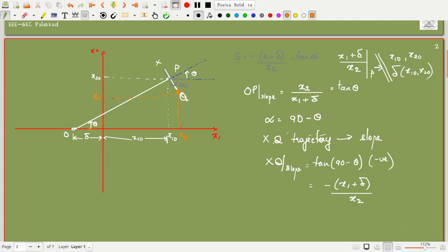Then I will draw the line here. It is not necessary to join these two lines. The only thing is that we have to mark this new delta point, with delta comma 0 as the center, and let me call this point O dash. With O dash Q as the radius, draw another arc. So from this line, we draw a very short arc again, and we got another small arc here, which is also in fact the slope at this point.